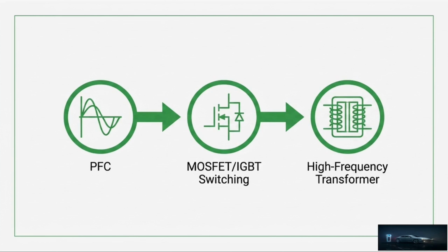So is PFC simply converting AC to DC? No, right? Its main purpose is to control the way power is drawn from the grid. Just keep in mind it's controlling the power that is coming from the grid.